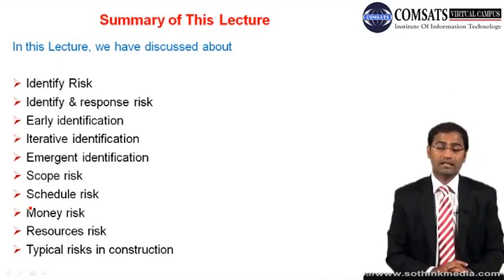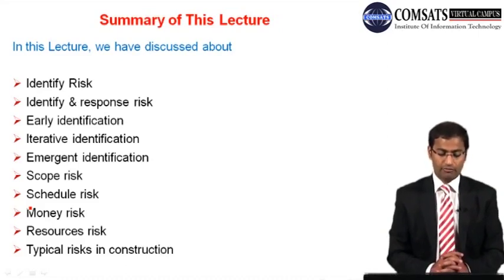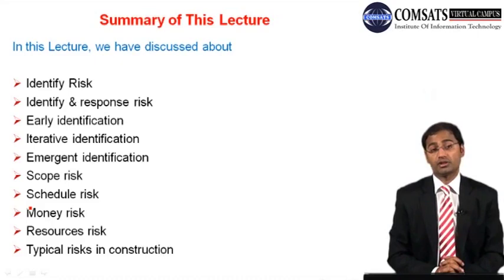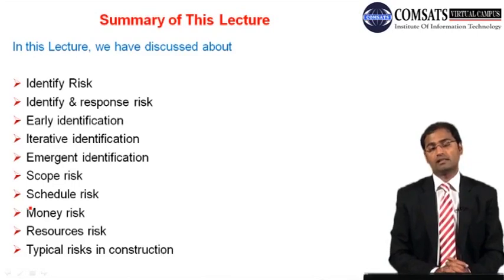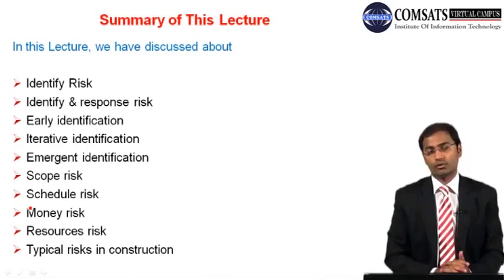We have talked in detail about scope risks, schedule risk, money risk, resource risk, and a few of the typical risks in construction as a case study of risk breakdown structure. And we have done that. The risk register is the output of that very process.